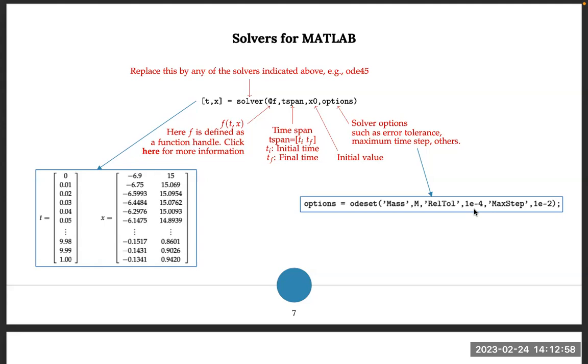You're going to say all these terms are related to the differential equations, and the rest is 0. So this is a diagonal matrix. The rest is going to be related to my differential equations. So implicitly, you're telling the ODE solver that you have some differential equations and the rest are going to be algebraic equations. So that's a way to do that.